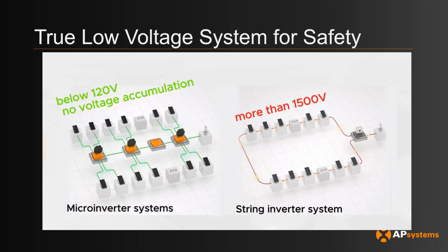In any case, for microinverter solutions, the maximum DC voltage you'll potentially get is a single panel. So if there are scenarios where you absolutely need a safe system with no high voltage arcing whatsoever, then a microinverter is useful, for churches or schools or something where insurance can be very expensive.